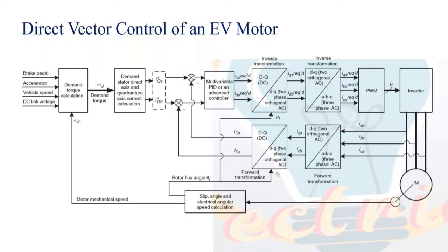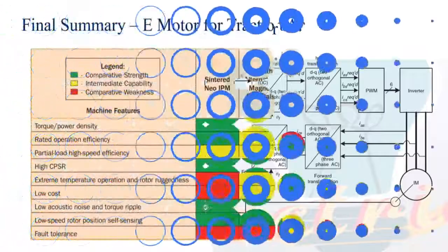In industrial applications, we call it triple VF. What is meant by triple VF? In our general industrial applications, we use this variable voltage, variable frequency type of control, which is not suitable for electric vehicle applications, because electric vehicles expect dynamic response. That dynamic response is not possible with triple VF. It is possible with controls like FOC and FOC maximum torque per ampere control.